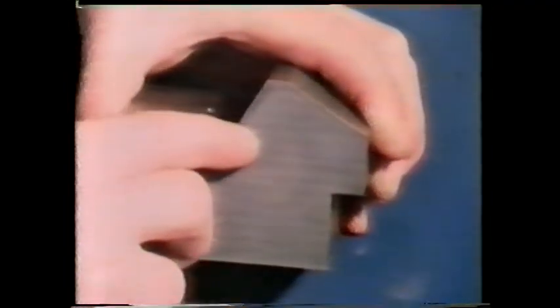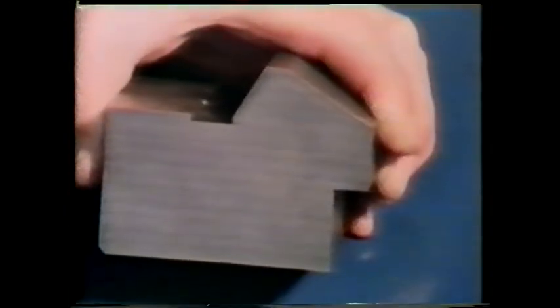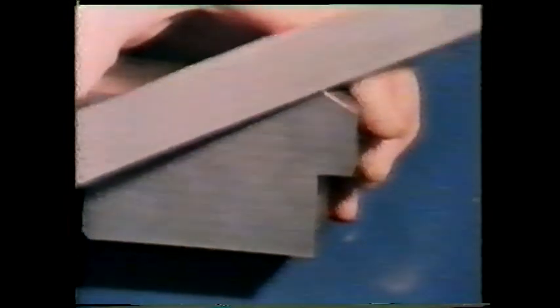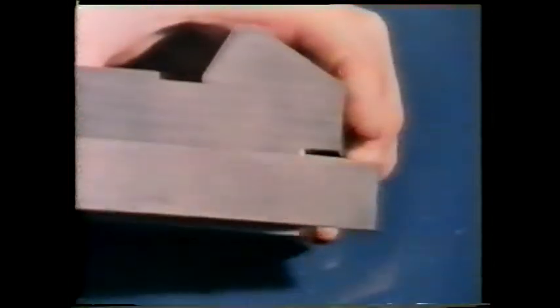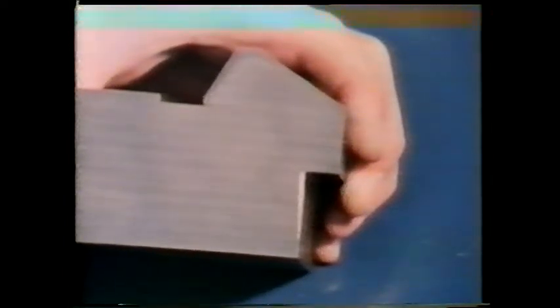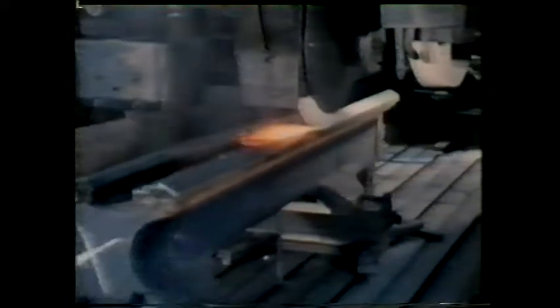If we look at a specially prepared cross-section through the slideway, you can just see the hardened area around the edge. We can test this with a file. Here it's hard. But here, where the metal wasn't heated and cooled, it's still relatively soft. Once a material has been hardened, any final machining must usually be done by grinding. This process of heating and cooling certain materials to harden them is known as a heat treatment process.